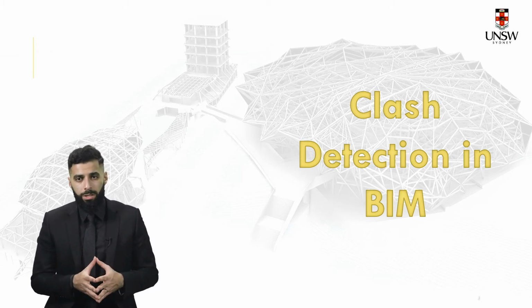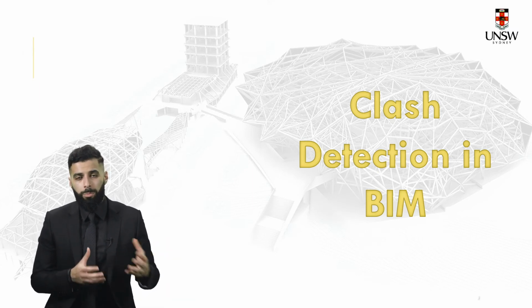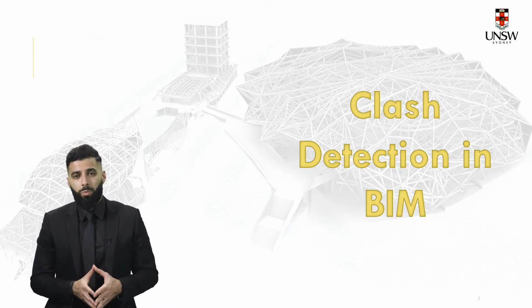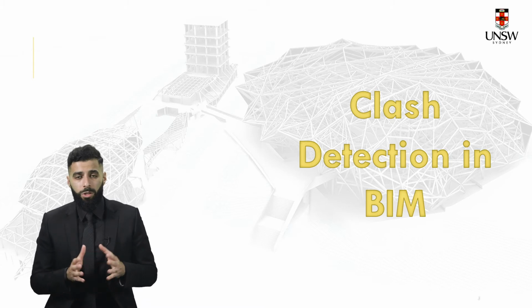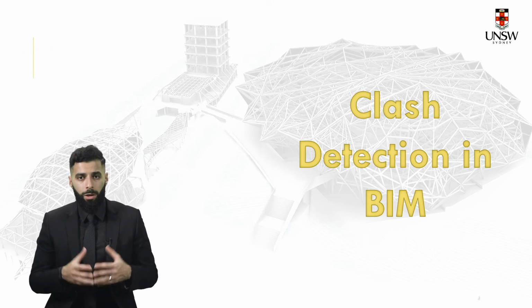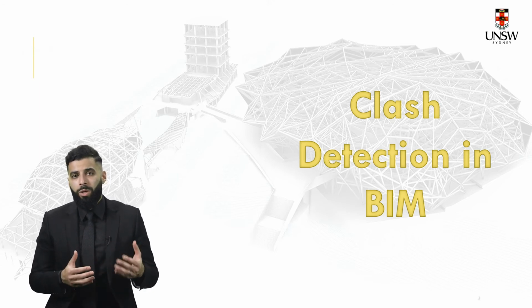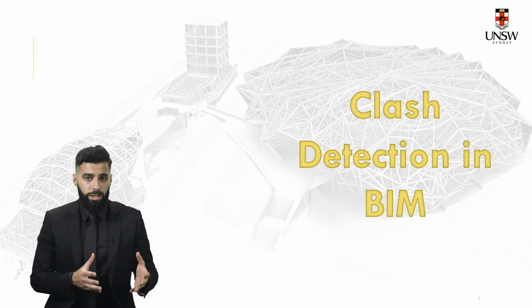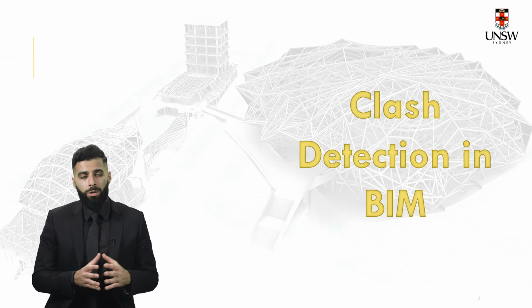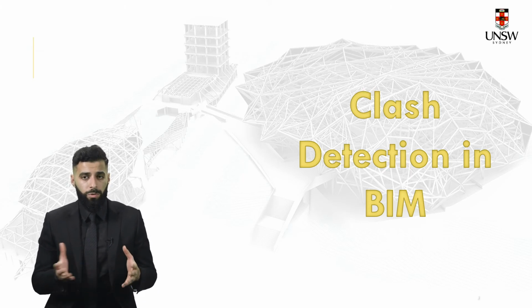Let me give you an example to make this clear. So, for instance, say you've got plumbing pipes that clash with, say, a particular structural beam that has to go on one of the levels in your project. Here, you would need to understand where that specific clash takes place. Specifically, this is important if you have a very big construction project with a lot of beams and a lot of pipes. And then you need to look at what sort of remedies you need to undertake in order to avoid that clash. And that can include maybe diverting the plumbing pipes or locating the beam somewhere else that is feasible.